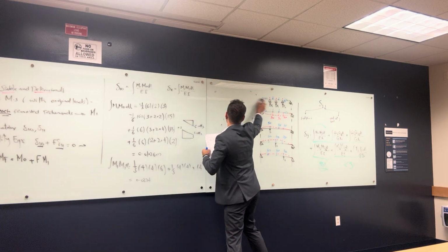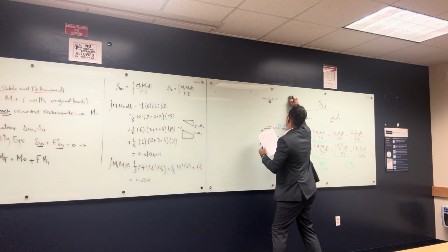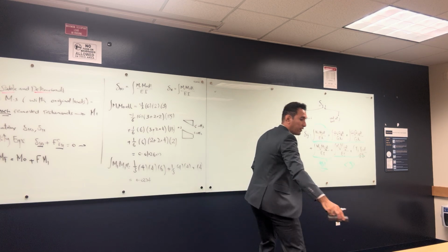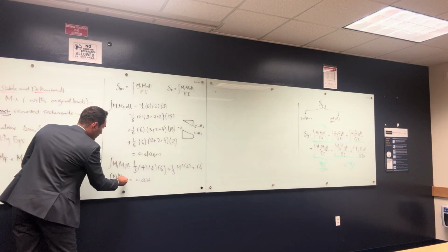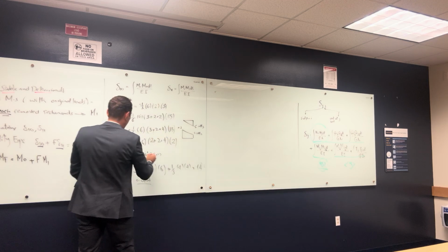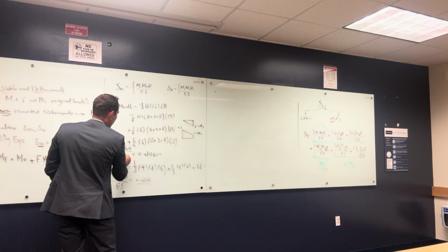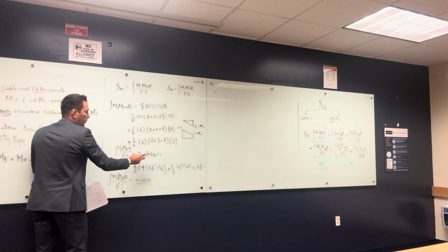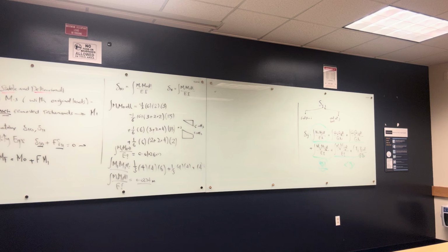All right, so we are done. We got delta, but by the way, I need to put something here. That's dividing by EI, right? Yeah, exactly, that's what I want to say. The value that I put here is the integration of M1 DL over EI. That's the final value, after you get this value. And the value that I got here is the integration of M1 MO DL over EI. I mean, after I divide with EI, like calculate this, divide by EI, you get this value. And once you are done, you divide by EI, and we already calculated EI here.